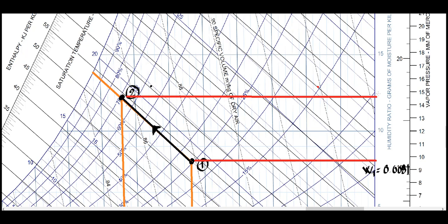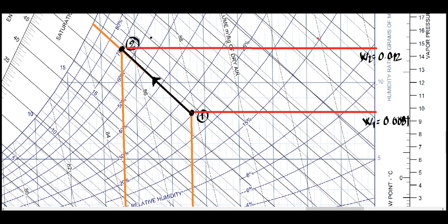Then you have your humidity 2, so this is 10, no? This can be humidity 2, 0.00. Oh, sorry. This is 10 only. 0.012, makes sense. So we have the values, so we can compute what is the change in moisture.